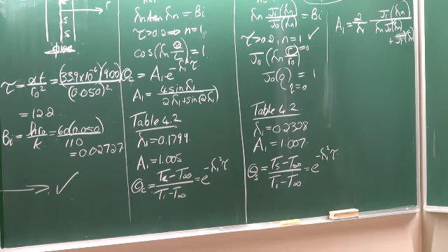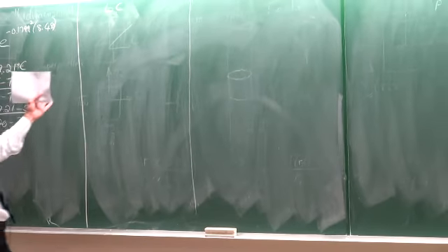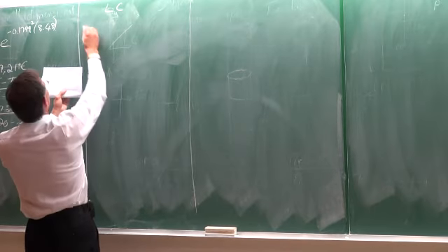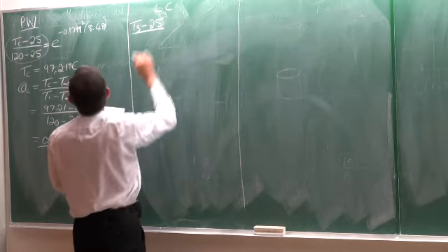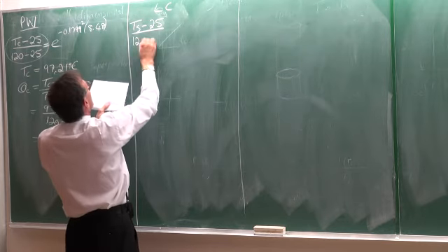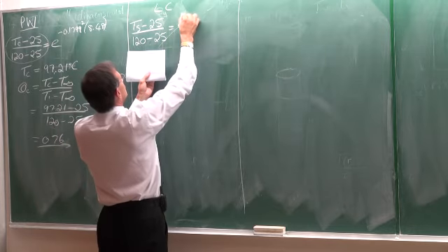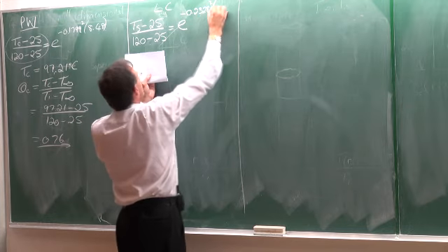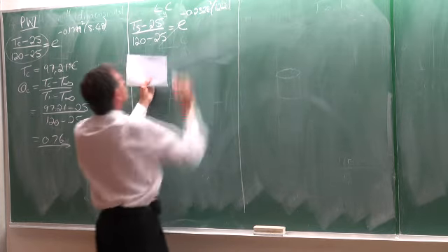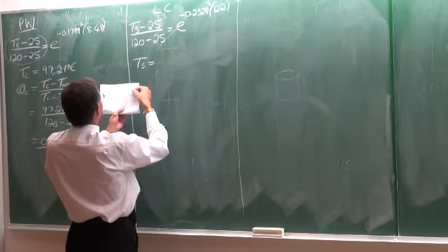So let's continue here, still with a long cylinder on the right-hand side of your page. And now we can calculate the temperature at the center minus T infinity, which is 25. The initial temperature, 120, minus 25, is e to the minus 0.2328 square multiplied by tau, which is equal to 12.2. And we can go and solve the temperature at S, which is equal to